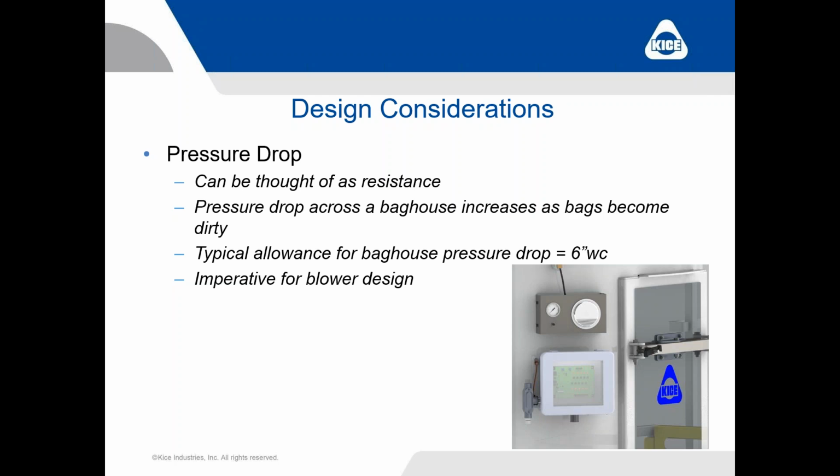So when your baghouse reaches 6 inches of water column, the baghouse isn't going to stop working, but what's going to happen is that fan is going to start diminishing in effectiveness. It's not going to have quite enough pull, quite enough guts to reach out and pull hard through those dirty filter bags. So you're going to start to see a negative effect in your dust collection system.